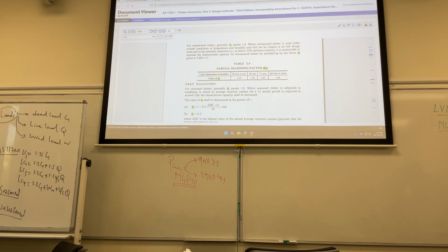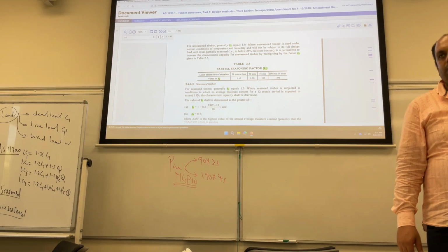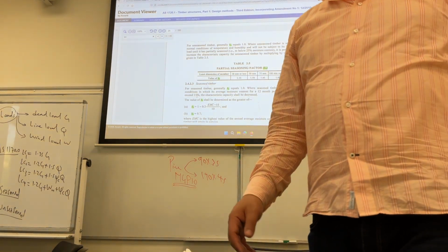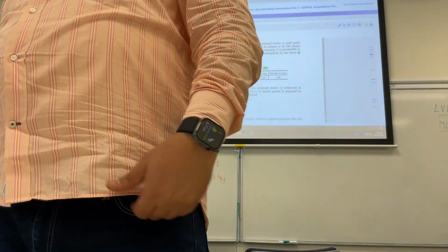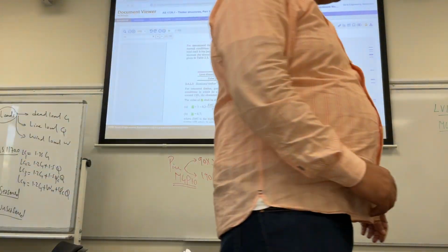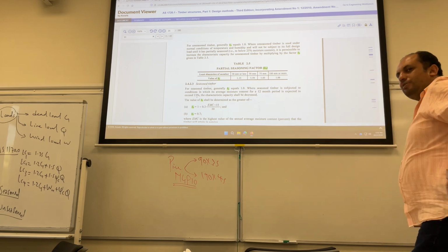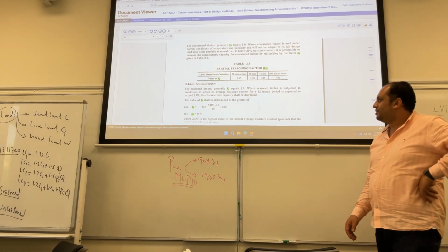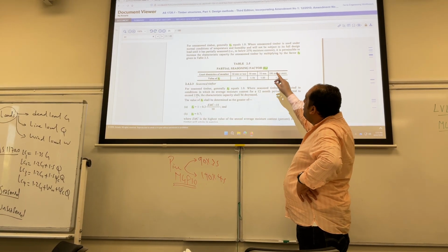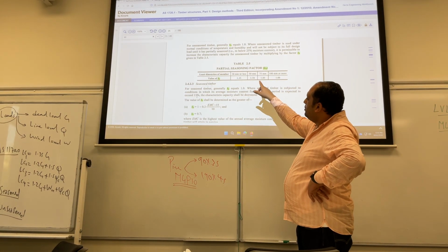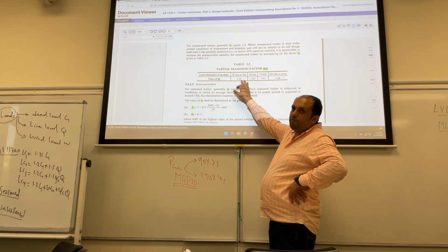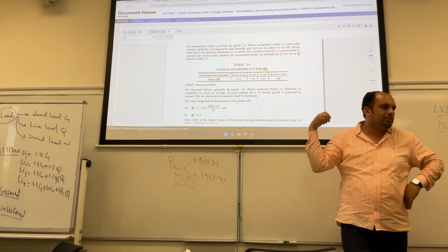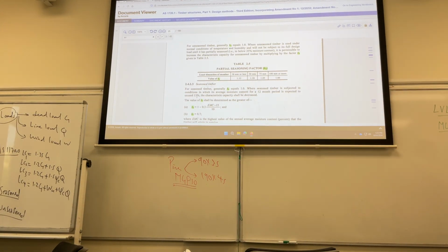But what you notice is that K4 is less than 1 for seasoned, and 1 or more than 1 for what? For unseasoned. Okay? So K4 is 1, up to 1.15, for unseasoned and 0.7 or we will calculate it for seasoned.